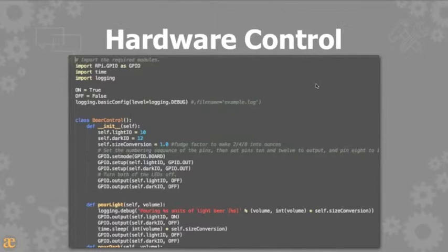So it's worth noting from a software development and design perspective that this is not thread safe. This is not multi-user. So we're using a multi-user technology. We made a website, with REST endpoints or just cleverly crafted URLs that you hit in order to control this hardware. So that's a multi-user environment. But here, our actual control code in the embedded system is not multi-user. So that's something that you have to be really conscious of when you make these kind of design decisions. You need to put something in place to ensure that only one user is going to use it at any given time.